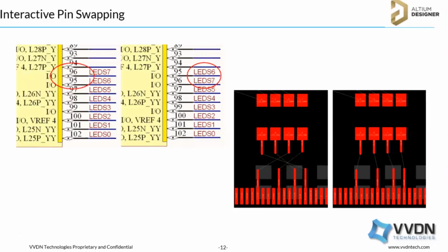And sometimes, this is a rare case, if you are not able to complete the routing, you need to swap the IO signals. This is a worst-case scenario. Sometimes we will face this if you are developing a very high-density board, even sometimes between the DDR signals, you have to swap the signals.